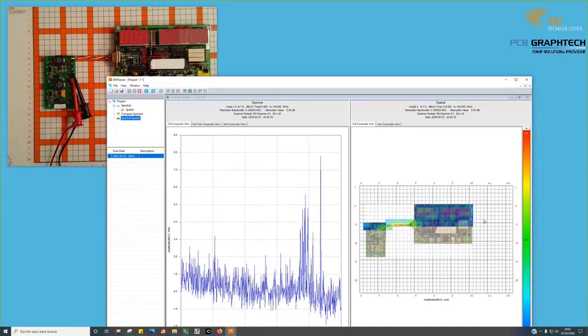Why? Because in the cable we have energy that is going, especially in common mode. We have two wires. The activity in differential mode is not creating big activity in the environment because of the cancellation effect, there is no loop. But the noise that is coming from the DC-DC converter that is exciting the cable in common mode is one of the most typical problems that I have found in commercial products when failing in radiated emissions. We are close to finish.